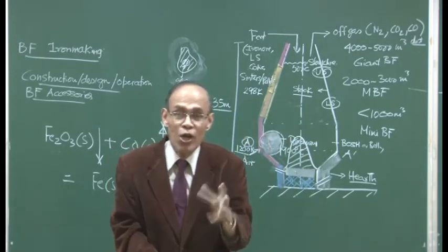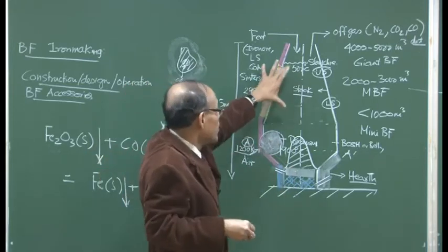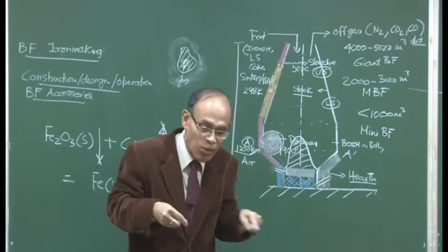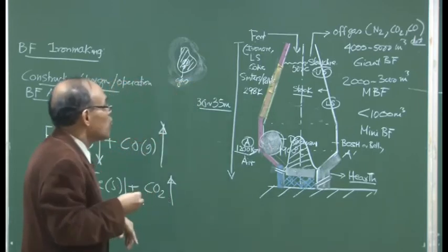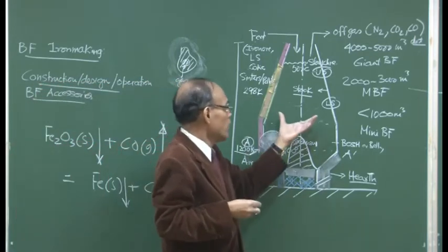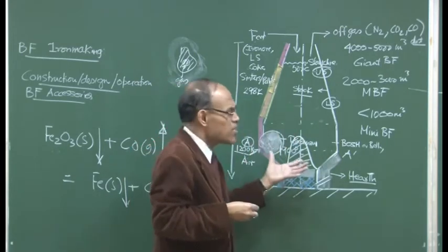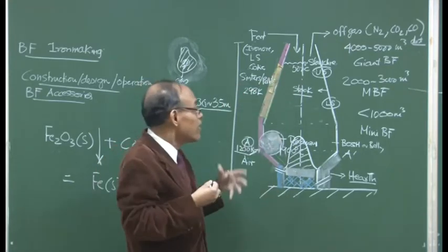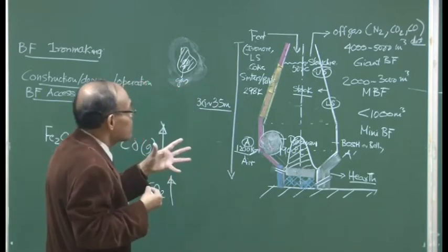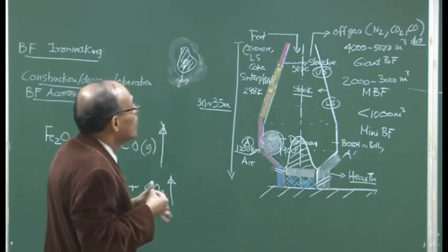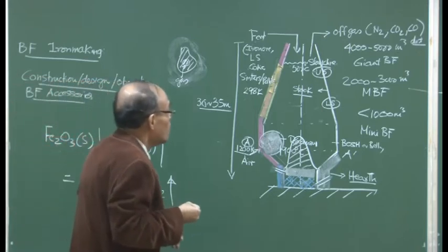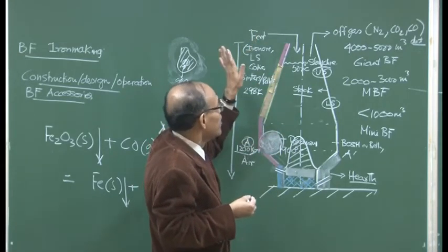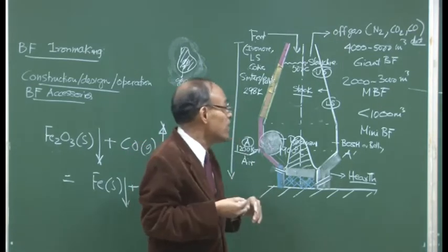The word permeability is used because you have solid particles here when you charge, and these solid particles touch each other, creating some empty space in between, through which the gas actually flows, and that is referred to as permeability. So, the more uniform the permeability of the bed is, the better. Some blast furnaces are very efficient, some are not, and it is because of all these kinds of paraphernalia, whether the bed permeability is the same or not, and whether the size distribution is according to the requirements of operation and so forth. So, if you just ensure that you are charging particles and not allowing gases to go out, that in today's context is not enough.